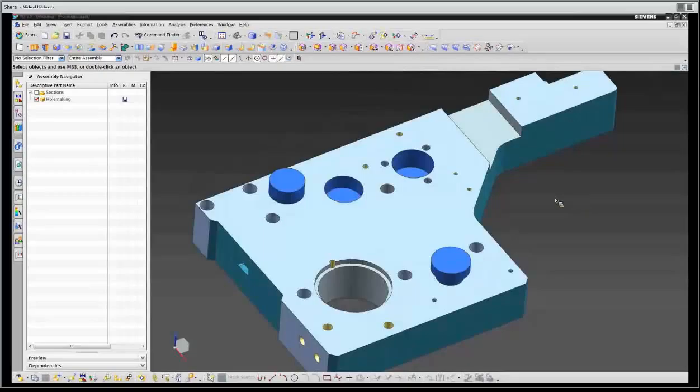And we could come in and drill this with the old standard point-to-point. Frankly, that'd be a little bit of work. Selecting the holes wouldn't be too bad because most of them are just on a couple of faces. But going through the process of getting the right spot drill and then coming back and drilling them with the right one, picking all the tools, setting that process up to go through that, deciding what size holes they are. A lot of control, but a little bit of time to do that. So what we would recommend in something like this is to go do it in feature-based.